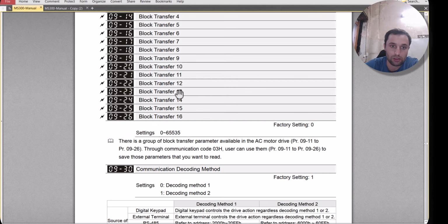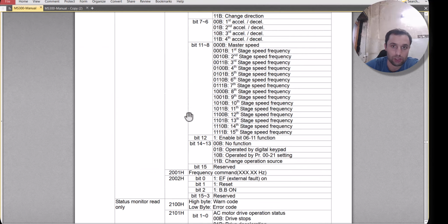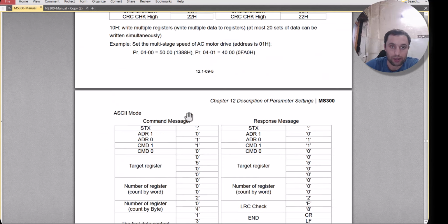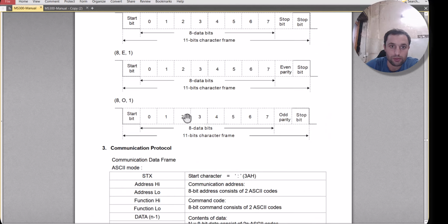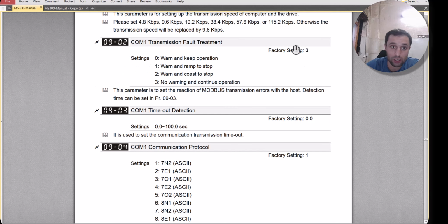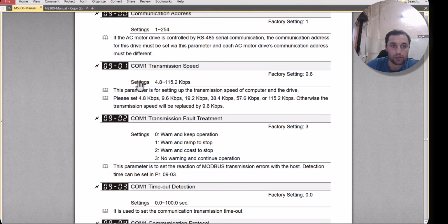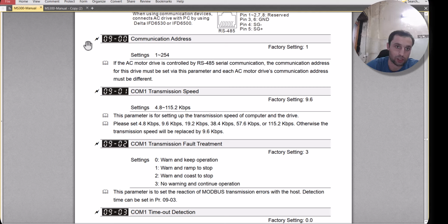So parameter 900 is the station address, and this address you can read by HMI. So first we will make one tutorial in PLC mode, but I will communicate by this VFD communication address. I'm just using the program inside the VFD, but only communicating these VFD parameters by HMI.